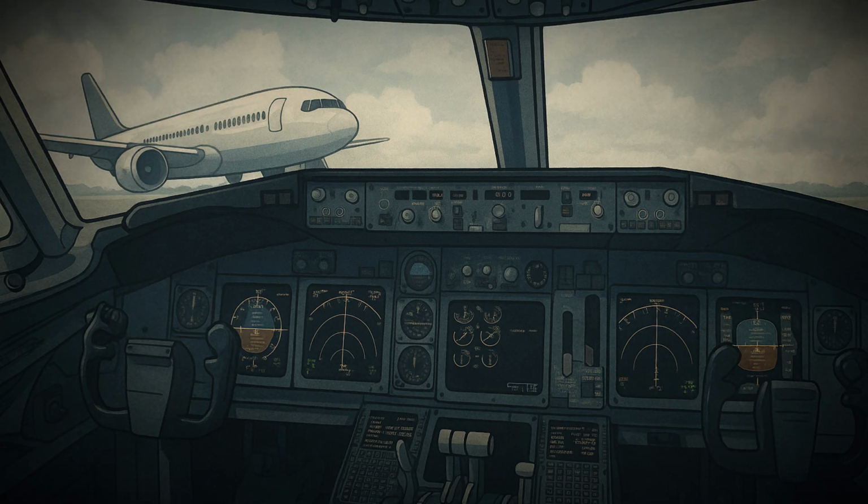Pilots retract flaps and gear quickly after takeoff to restore aerodynamic efficiency. Similarly, adjusting speed and altitude affects drag. Flying at optimal cruise speeds and altitudes ensures that drag is minimized relative to thrust, maximizing fuel efficiency.